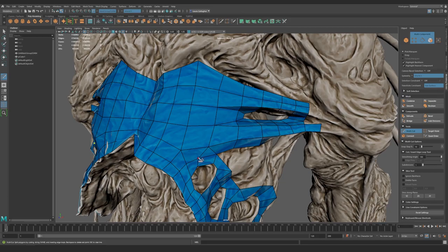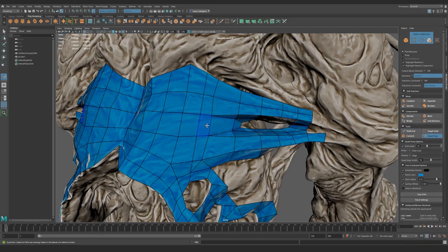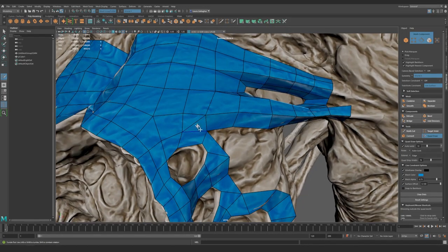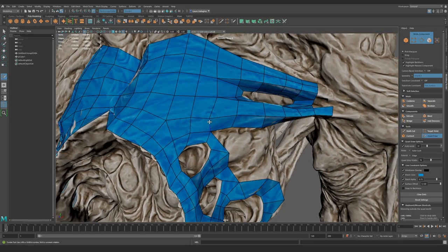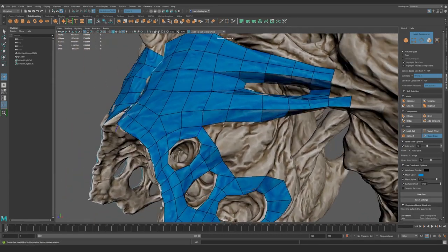It's very tempting to continue this particular edge towards the top there. It kind of allows us at the bottom to be able to quadrify the whole mesh. Let's do a bit of a relax here to uniformly spread those vertices, and then we can get rid of this particular edge afterward. And here we have a bunch of nicely square quads. So it's very, very nice as a way to resolve that.